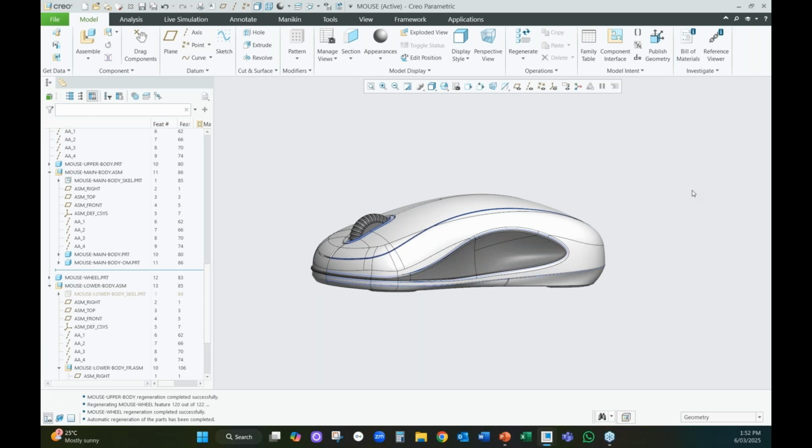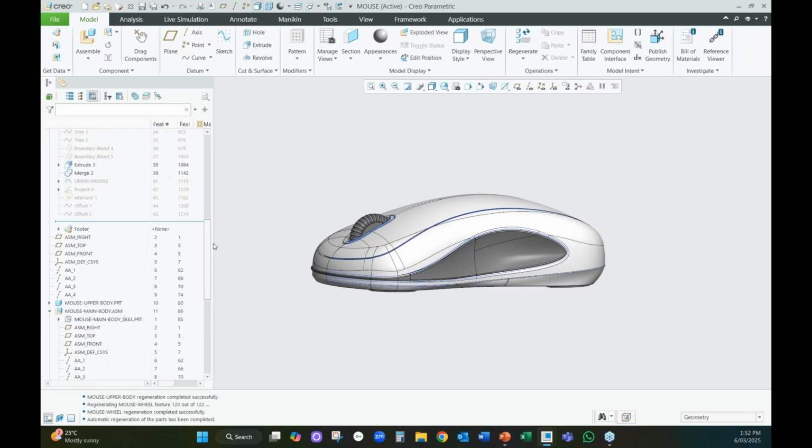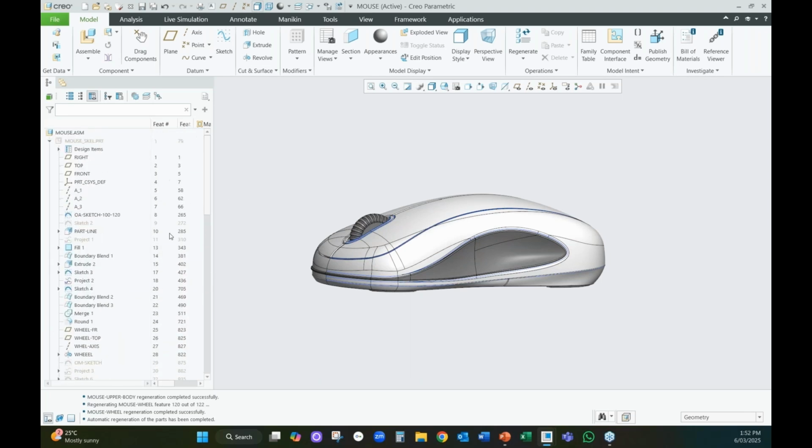Then you move in and out, up and down through the model tree, and certainly having these identifiers of the feature ID numbers helps. And they will be identified when features fall over. It'll say F for this sketch. If it falls over, it'll be F20 and ID 705. So you can then use your search functions to go and find that.